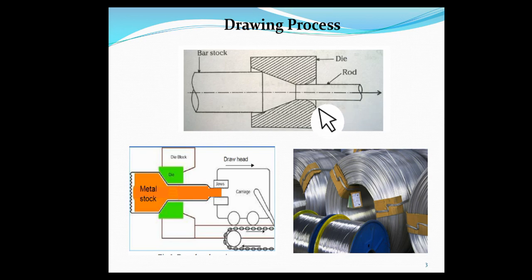Once the reduction in thickness takes place according to the required design based on the application, it will be moved for the secondary operations. So this is the operation that we are going to write in the exam. The first step, remember, is that based on the application the raw material will be selected, then the entry portion will be squeezed to a certain length, then it will be gripped by using the jaws and also the external equipment, where you are going to see the carriage and also the chain drive.